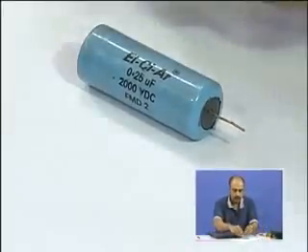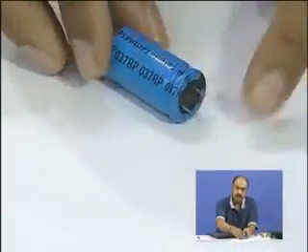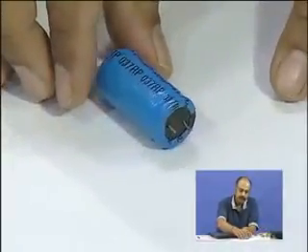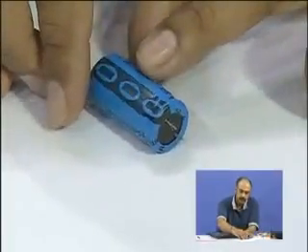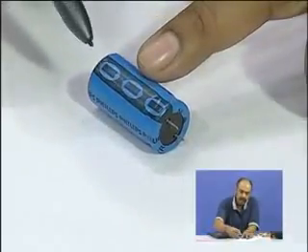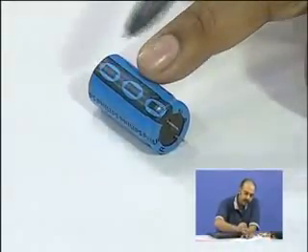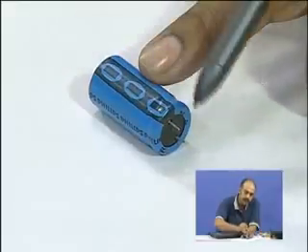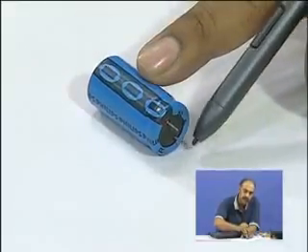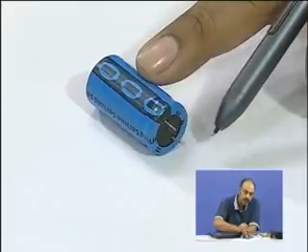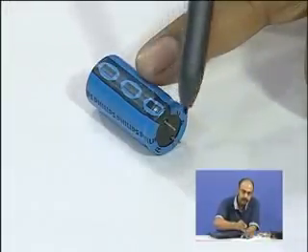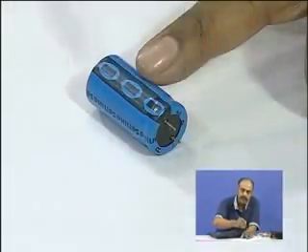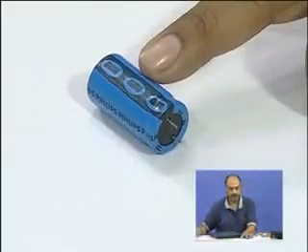I will also show you another capacitor. This is an electrolytic capacitor, polarized, of similar size. You see here the two terminals and see here the marking, the minus marking, which means this terminal which is closest to the minus marking is negative and the other terminal is positive. So, that other terminal should be more positive than this terminal. So, always look for a polarizing mark on the capacitor which says that that terminal should be either more positive or less positive than the other terminal.